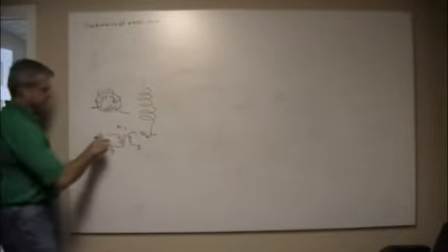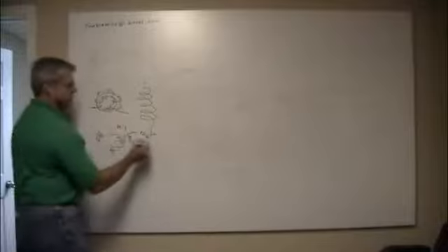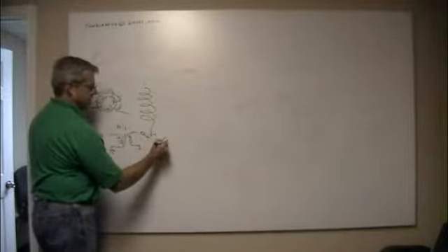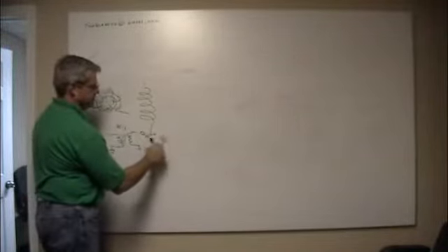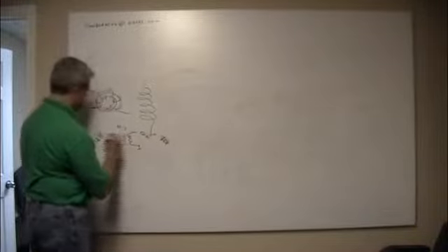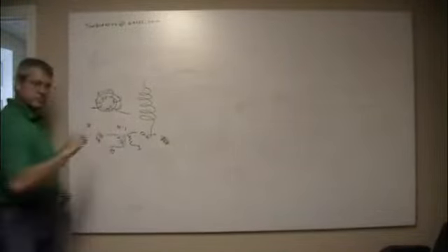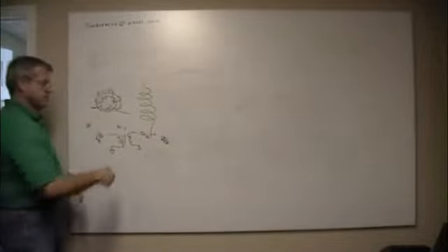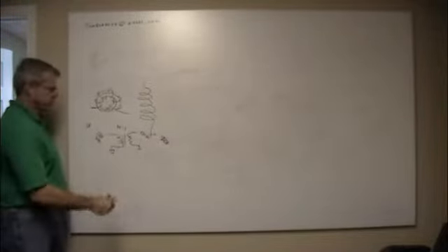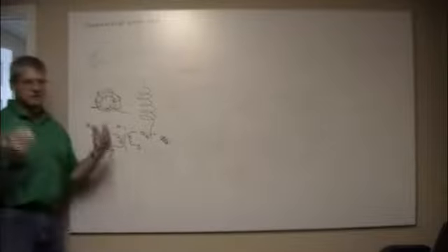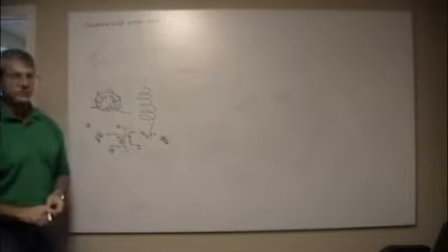The other thing that happens here is you transform current. So if I draw 10 amps on this side, I'll be drawing 1 amp on this side. So conservation of energy, total power has to stay the same going through, minus some inefficiencies. It's like 98% or better efficient.